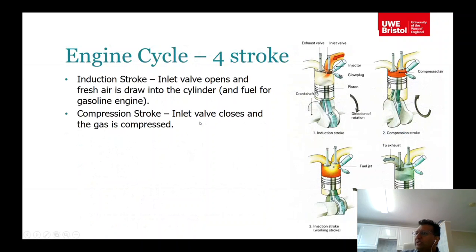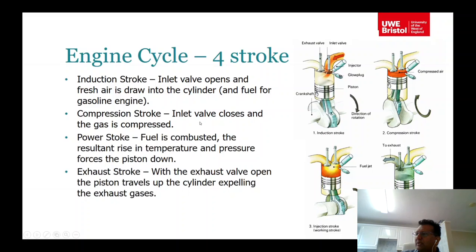In four-stroke engines, as I said, you have the suction, compression, power, and exhaust. Suction is called the induction stroke: the inlet valve is open, the exhaust valve is closed, and you suck the air inside. Then both valves will be closed at the end, and you have the compression stroke where you compress the air-fuel mixture, or the air in compression ignition engines.